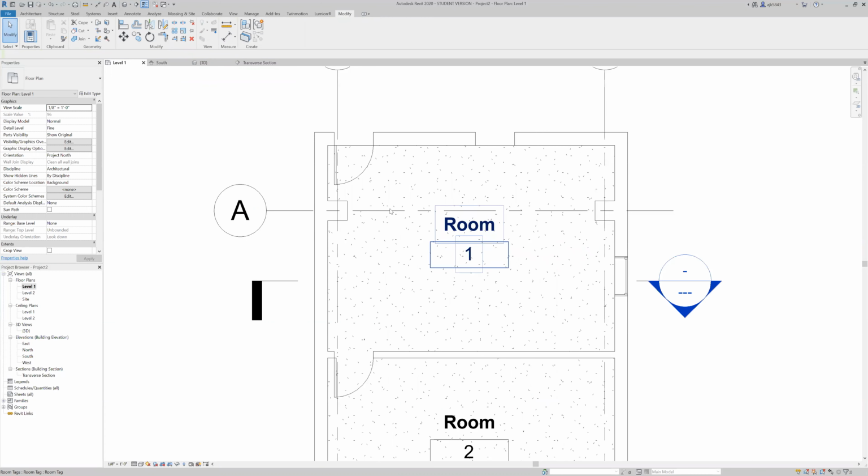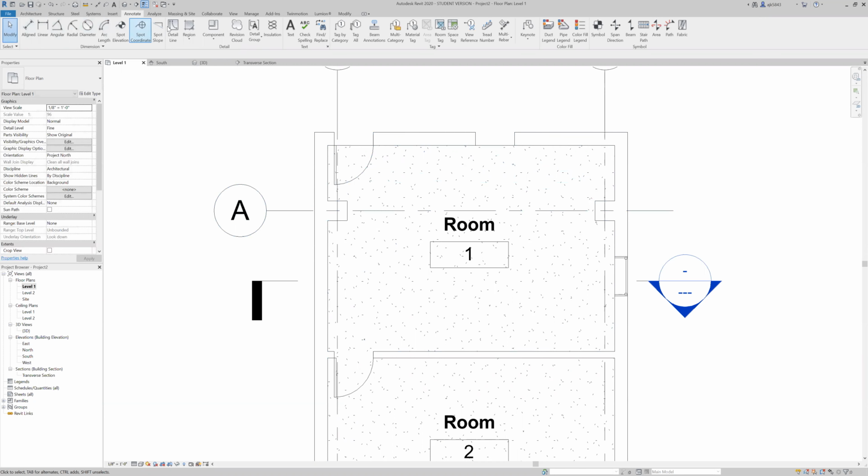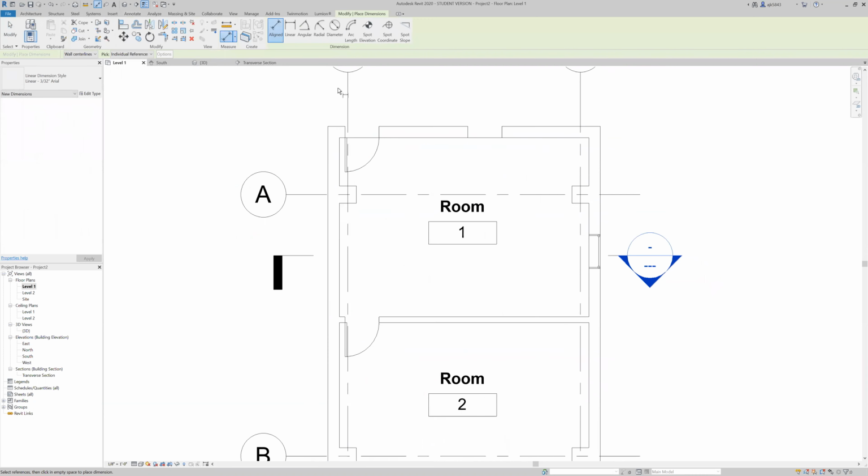In plan, there's a couple of different things that are good to know. Also under this Modify tab, we have the measure between 2 references. So if we pick the inside of this column to this one, we'll notice that that's 19 feet. What it does not do is that it does not leave an annotation string. There's a separate tab called Annotate where you can find all of the different annotations. So this is a great way to measure the interior of your space.